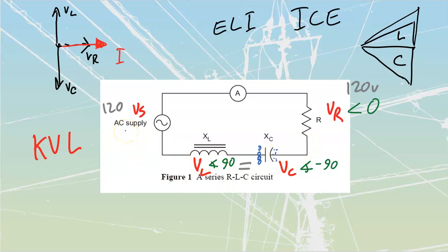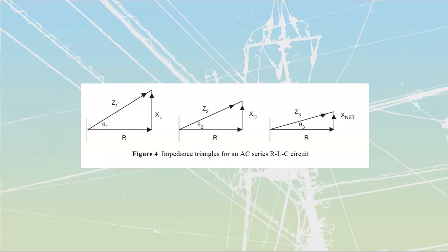They're feeding current back and forth from one to the other, which means that since there's current going through there, they will still have voltage drops across them. What we're going to have as well is an absolute minimum value of impedance in our circuit when we are at series resonance. And the reason for this is we're just simply at the very smallest triangle, right?